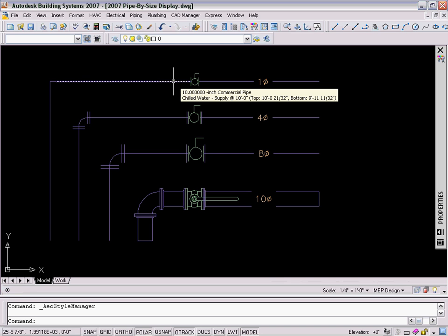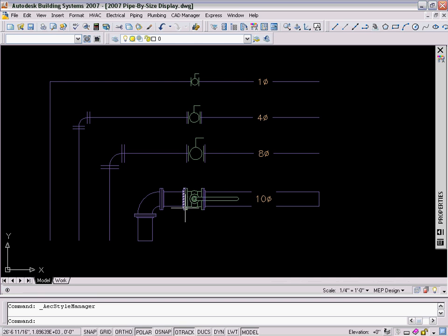And the reason why this is instated is in an instance where we may have upwards of an 18-inch valve here that's going to be quite large. If the scaling is set so that that doesn't display too large, most likely if we were to display an unscaled version of the valve here in a 4-inch or a 1-inch, it's going to be so small that when you plot it out on a viewport, it's just going to look like a blob. So basically, when we change the plot length, that allows us to have a symbol that's readable on the drawing.